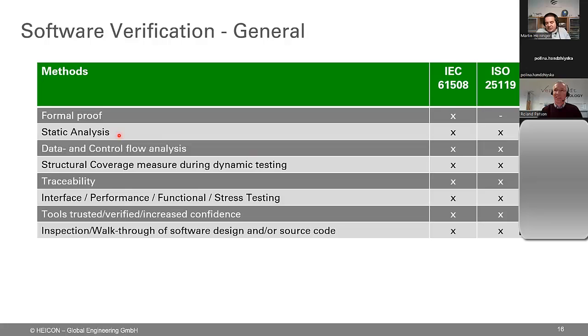Static analysis is actually, to some huge extent, MISRA checks, and I will show you the runtime errors in a second, on the next slide. This adapts to static analysis. Then the point data and control flow analysis is mentioned in all the standards, but nobody in industry, or only few people, take it really seriously and do a lot on this analysis. But I'm pretty certain this analysis will get more and more important as time goes on, and the standards are developing, and assessors are keeping more and more an eye on the data and control flow analysis. I will show you some more details in the next slide.